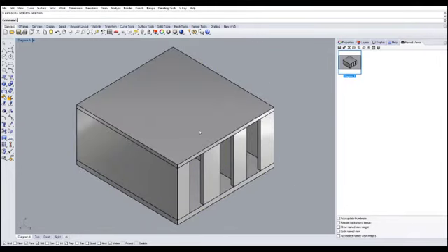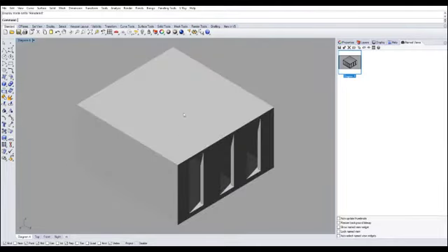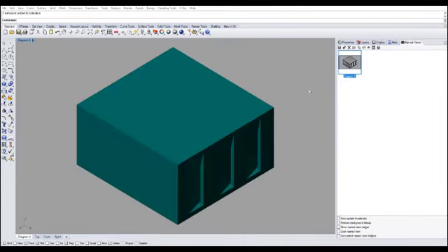Now, right now it doesn't look like anything's been done to your model, so per usual you have to slightly change your view so that it gives you the preview of the material that you're applying in V-Ray. So I'm going to go back to the View tab, click on that little right triangle, and right now it's set to shaded. If you click on the render mode, it changes to the material of the V-Ray. So to check that this is indeed the V-Ray material that we assigned, all you have to do is simply make some changes to its parameters, and there you have it, it is changing. Let's go back to white.